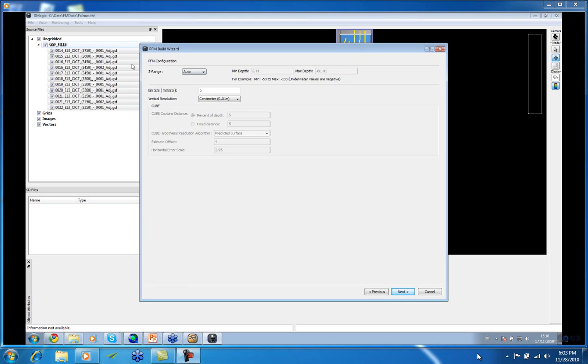And if you, again, want to include data which is outside that range, then you need to specify the potential maximum range of the data. It's not a problem to specify quite a large range because it's not going to take up too much space. But if you're doing shallow water work, you know you're never going to be deeper than 100 meters. So do it from 0 to minus 100, and then you'll always be within the range.